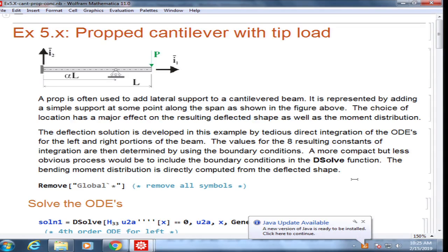So let's think about what's happening in the middle. We'll start with displacement. So any idea about the displacement? I'm just explaining that the reason there's shear at the end of the beam is because the shear will be up and it's going to be canceled out by P, and then the sum is 0 at the end. So we are applying the equilibrium at the right end, and there should be some shear force V2, and P is applied. If the P was not there, we'd say that shear force is 0. So that's standard, we already know, right?